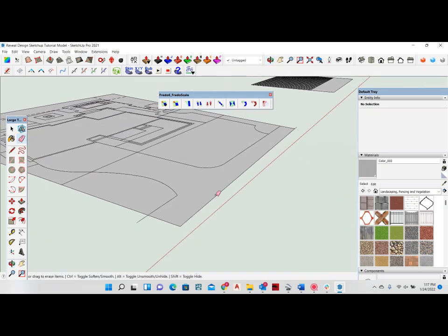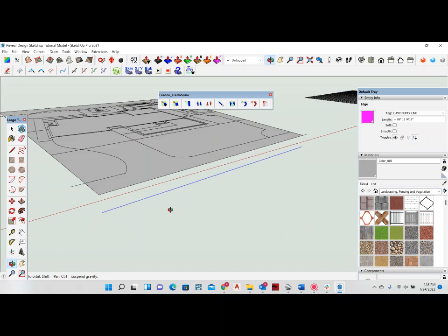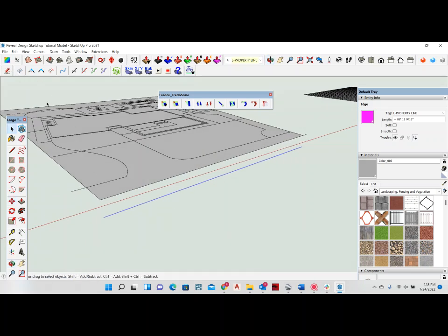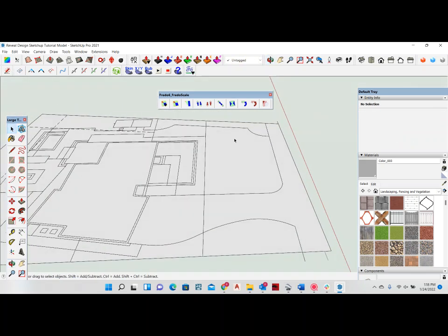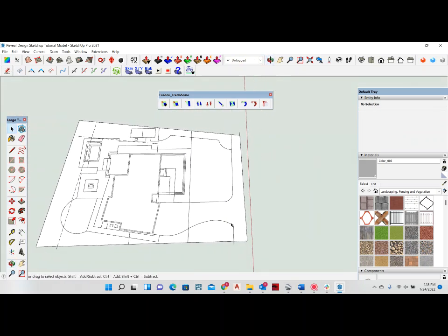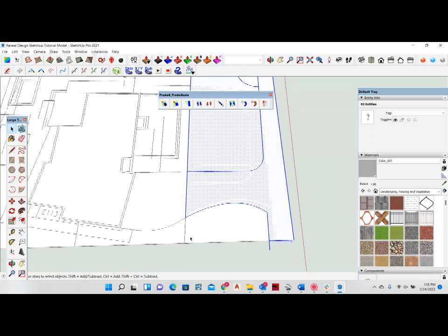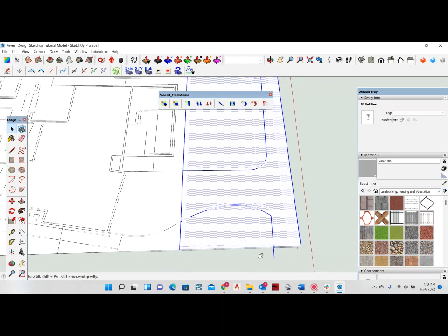And what I do need to do is determine how far down I want to slope this. So what I'll do is grab my selection tool, move copy, bring this down. I'll make a copy of that, bring this down about 5 feet or so. And then I'm going to go ahead and select everything that I want to slope. So I'm going to grab my selection tool, drag that, should grab that one, should grab that one.